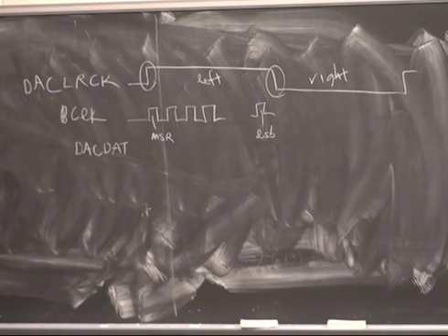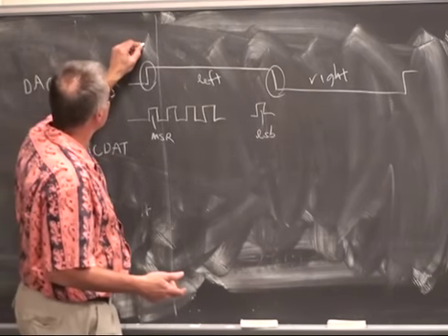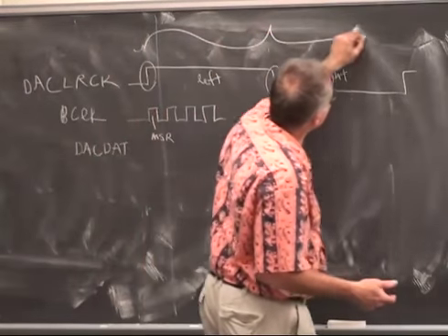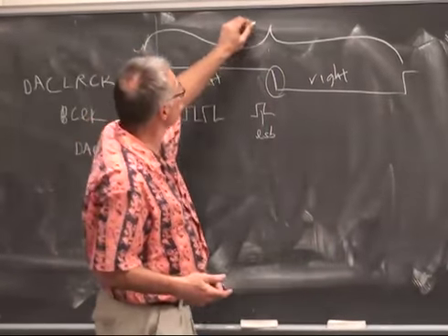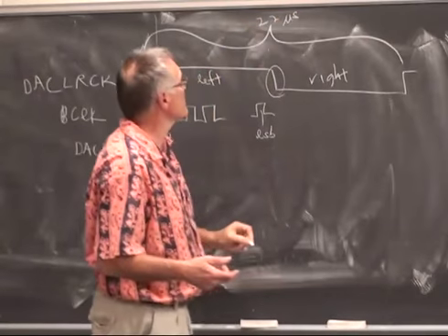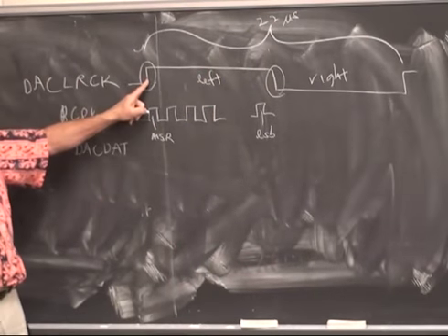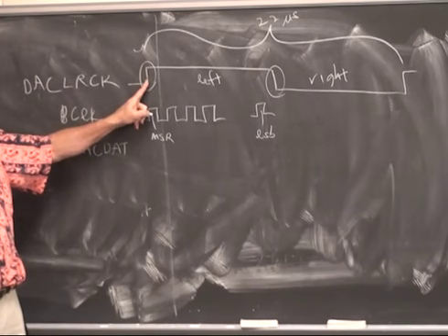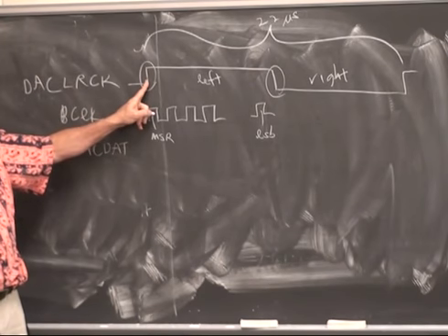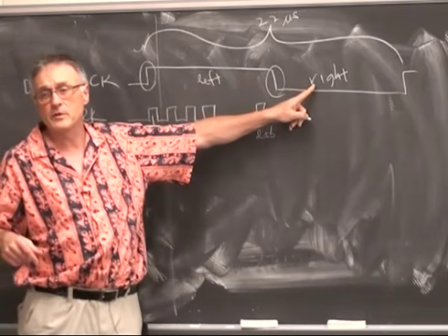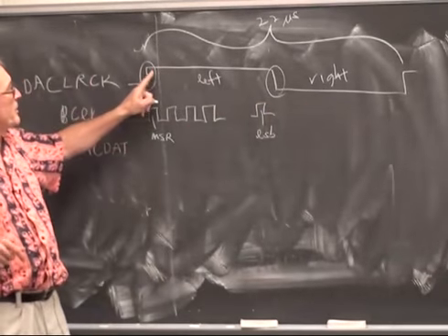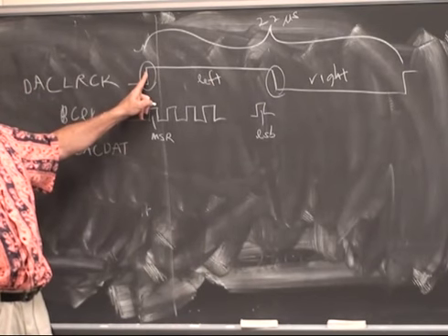Whenever you poll on a CPU, you're assuming that you have enough cycles that you can poll quickly enough that you don't miss the event. So we have to ask, how much time do we have here? Well, this whole time at 48 kilohertz must be about 22 microseconds. And so you have to get a new edge on each of the two CPUs. You have to get a new edge each 22 microseconds. Remember, one CPU is going to be doing the left channel, another CPU is going to be doing the right channel. So each CPU has to notice an edge in about 22 microseconds.